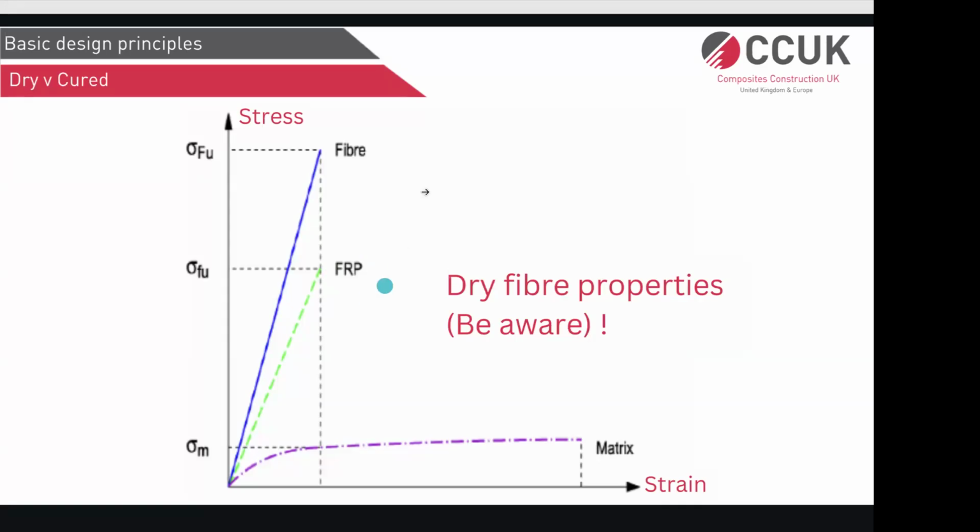There are still people out there who do design based on dry fiber property, which is okay. You could do that, but there are many other safety factors you should use in there. But ultimately, if you're using a fabric system, it is best practice to design it based on the final cured laminate property.